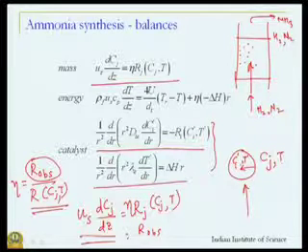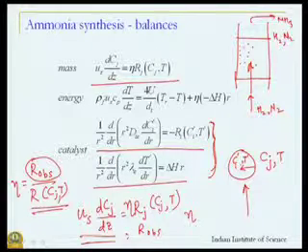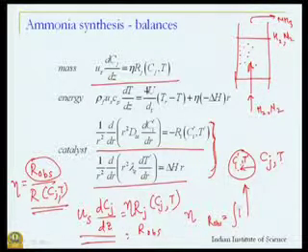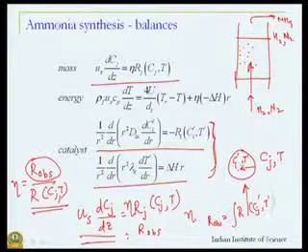Now, there are two ways one can simulate this. If you know the effectiveness factor a priori, put that in. Or if you do not know, then at each simulation time step we will have to solve these equations for the catalyst pellet and evaluate the effectiveness factor. Or if you do not want to evaluate the effectiveness factor, just evaluate the average rate.